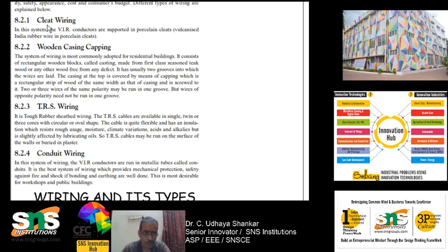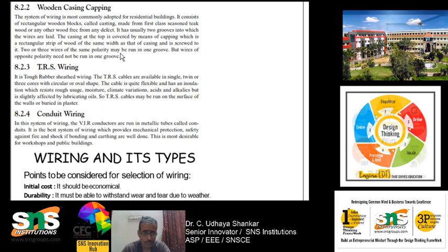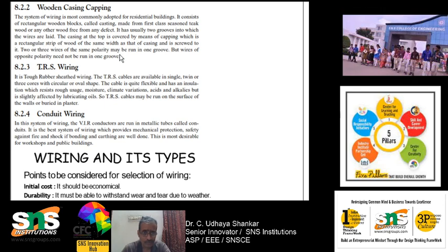So what do you mean by cleat wiring? These were all used in very early days. In this system, the VIR conductors are supported on porcelain cleats. These are normally not used nowadays. Wooden casing wiring is also not used nowadays.